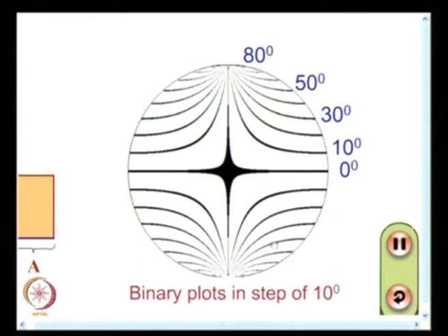In fact, when we do the chapter on photoelasticity, we will know in detail what these isoclinics are. Iso means constant, clinic means inclination, so isoclinic means contours of constant inclination. Constant inclination of what? Constant inclination of principal stress direction. So, from a photoelastic experiment, it is possible for me to get sigma 1 minus sigma 2 contours, and you can also get, by an appropriate optical arrangement, contours of principal stress directions.